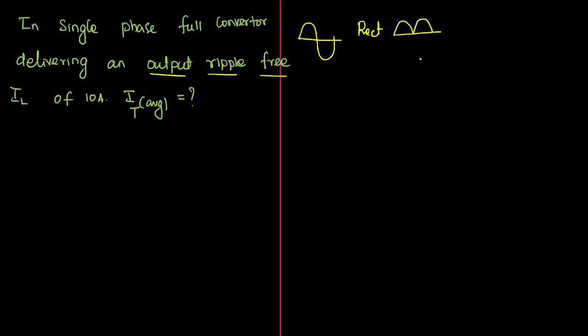Then what will people do? People will keep filter circuits here. What filters? Basically, we use a capacitor. I will clear this doubt here. Listen, assume there is one load, and across the load I connect a simple capacitor. Now tell me what will happen. Initially, the very first time you charge this circuit, the capacitor will charge. But remember, the output is pulsating DC only, so basically it is a DC waveform. When a capacitor is connected to a DC supply for a very long time, what will happen?